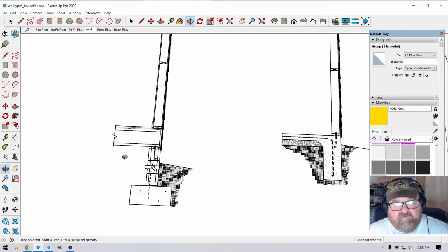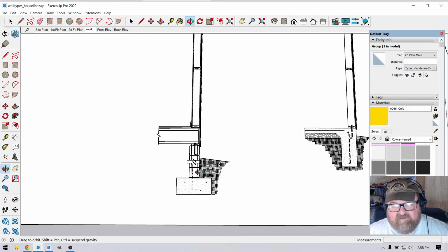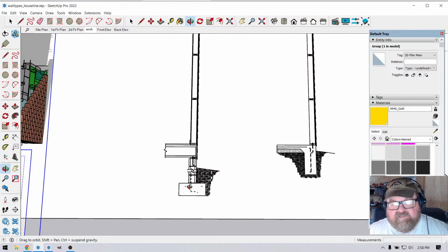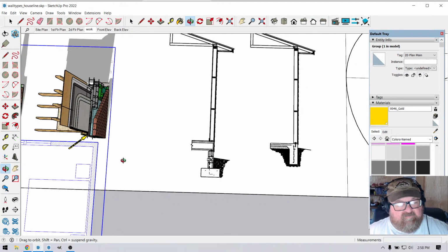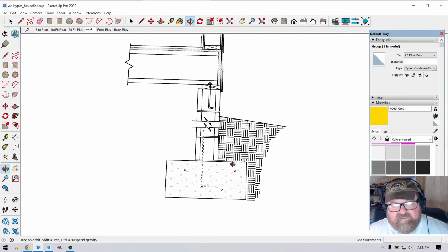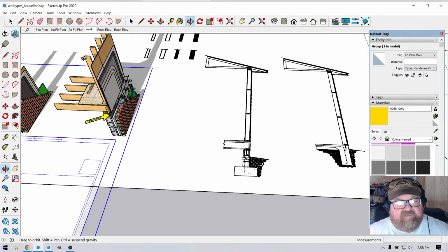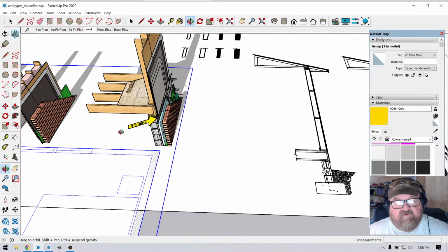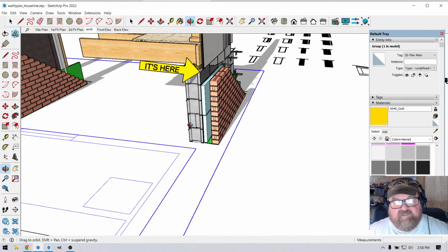This is one with a crawl space, and this is a turn-down slab. This is how we represent different types of wall sections in architecture. Now, I don't show the footing, but it's down here underground. You can see the concrete block in this case sits on top of a footing. So pretend that's under the ground, and the footing's under there. So this is sitting on there.